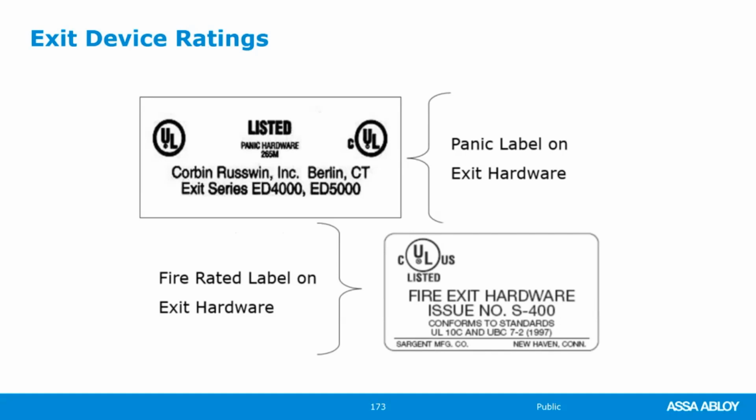Now, I will harken back to our NFPA 80 discussion a few minutes ago. NFPA 80 states that you cannot use a fire-rated device on a non-fire-rated door.